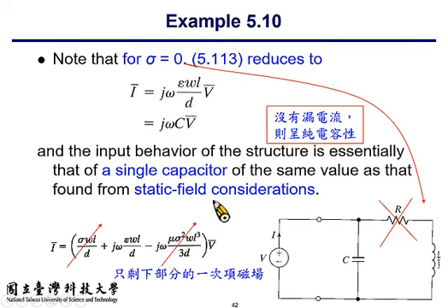And if you include more higher order terms, then as the frequency still goes up, you will come back to the capacitive property. So the component property is frequency dependent. It may alternate between capacitive impedance and inductive impedance.